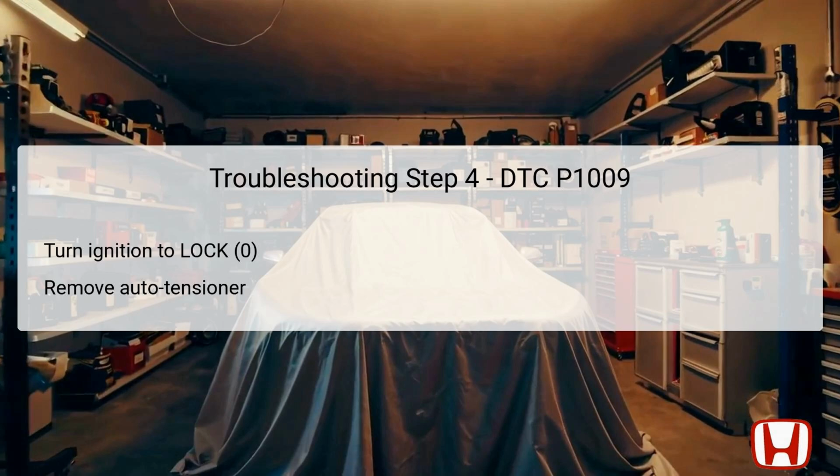The auto tensioner is a component that maintains proper tension on the engine's timing belt or chain, ensuring that it functions efficiently. Its removal is crucial for accessing the VTC components that may require inspection. This mechanical disengagement step enables technicians to access the VTC strainer and other components, essential for identifying potential clogs or faults that may be causing the DTC P1009.